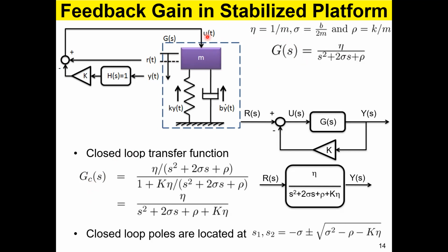There are so many internal signals. It's an important signal, but what we really want is to figure out the relationship between RT and YT. Okay, so that when you change your reference, the table will follow it. Let's say you set it to 1.5 centimeter. In about 20-30 seconds, the table will go to that level and settle. And then you immediately change the reference to, let's say, 4 centimeters negative. In about 1 minute, the table will go to -4 centimeters and settle there.